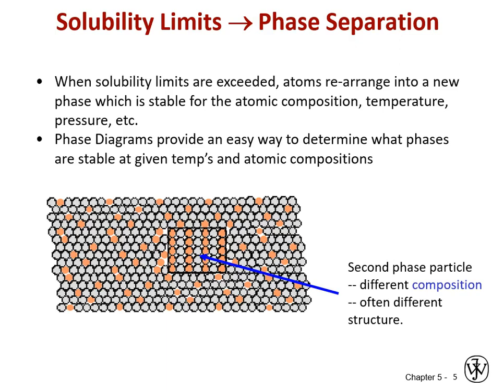They tend to be very hard, very strong. They tend to have properties that are quite similar to ceramics, and in fact share a lot in terms of bonding, even though they're metals. And so those will spontaneously nucleate under certain conditions of temperature and pressure. And again, that's in response to lowering the material's overall energy state, and it's a chemical drive more than a strain energy drive. So that's introducing a new concept in terms of energy, chemical energy driving material changes, not just interatomic position on that potential energy diagram.